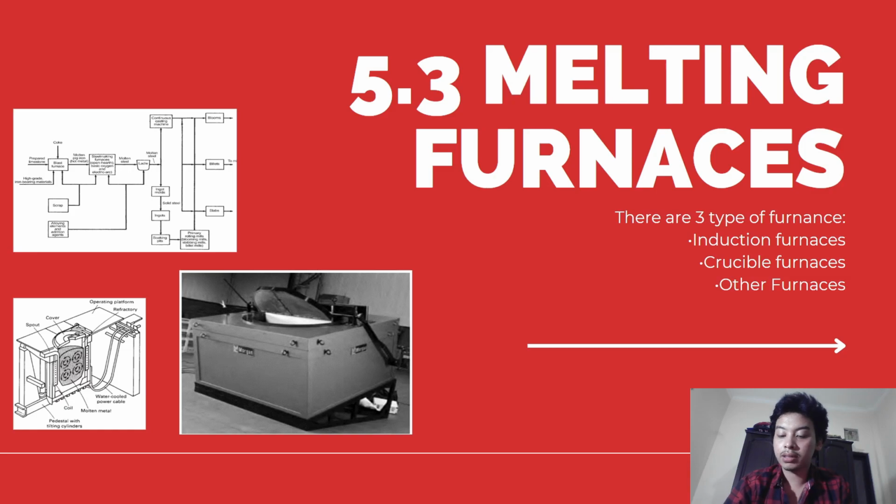Because it contains excessively high levels of silicon, manganese, carbon, and other elements, this liquid iron, together with scrap and fluxing agent, is then introduced into either a basic oxygen furnace or an electric arc furnace for further refining with oxygen. The objective is to reduce silicon, manganese, and carbon to acceptably low levels in the resulting steel.